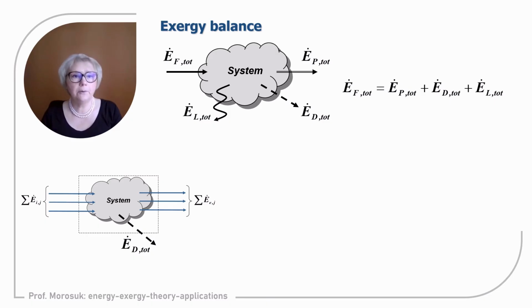We already learned from the previous lectures that we can conduct exergy analysis in terms of in-out exergy, but it is the old version of exergy analysis and will not give us an appropriate definition of efficiency, exergetic efficiency. It is better to conduct analysis in terms of exergy of fuel and exergy of product. Regardless of which method we apply, the old method or the new method of exergy analysis, the term of exergy destruction will be the same. So irreversibilities will be defined absolutely correctly using the two different methods.